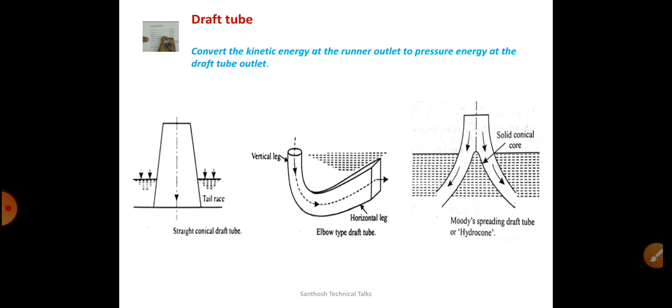So it cannot produce any disturbance or any floods in the outlet flow, whereas these reaction turbines use both pressure as well as kinetic energy, and can create a flood in the outlet pipe if it is not made with the draft tube. If the draft tube is there in the reaction turbine, the floods are being controlled.